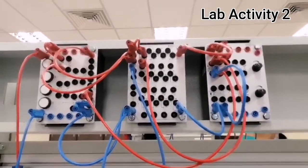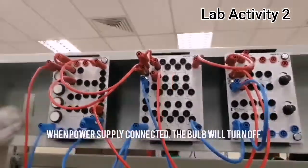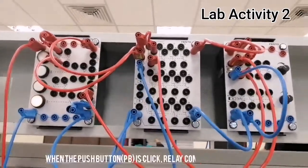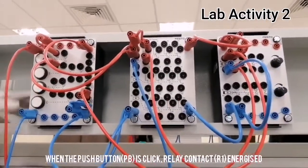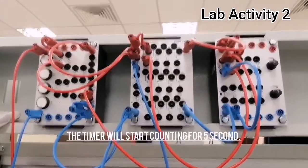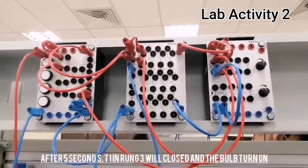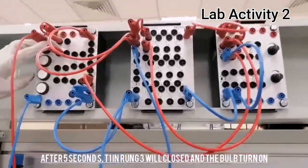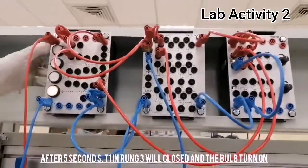For task 2A, when the power supply is connected, the bulb will turn off. When the push button PB is clicked, relay contact R1 energized. The timer will start counting for 5 seconds. After 5 seconds, T1 in rung 3 will close and the bulb will turn on.